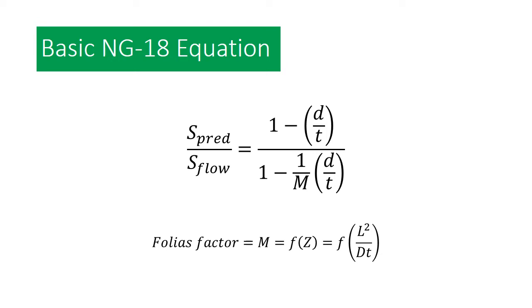You will notice that the equation has been stripped down. It doesn't have any shape factors in it or correction factors that you might be familiar with in the ASME B31G equations. If you look at original B31G, you'll find that there's a 2/3 factor in there. If you look at the modified B31G, you'll find that there's a 0.85 factor in there. I've stripped this down just to keep things fairly simple.